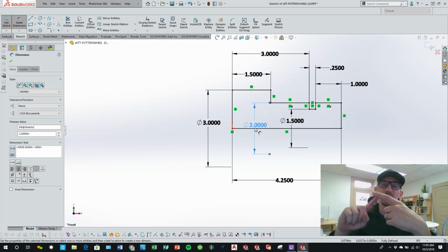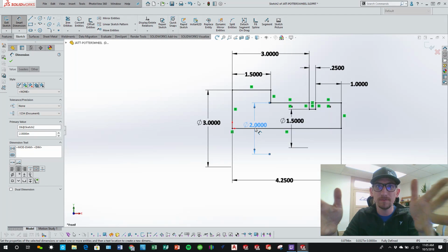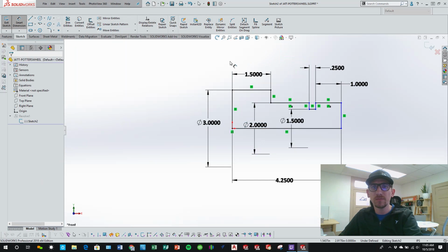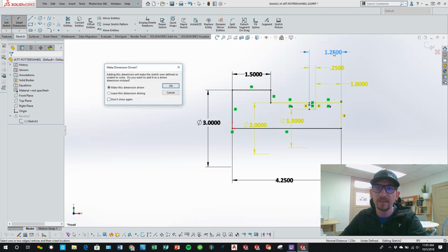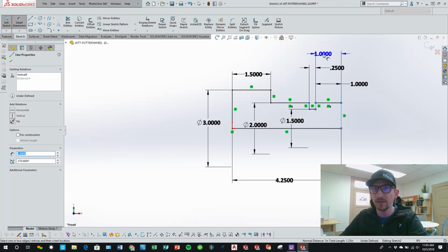Okay, so moving along here, this is a very good pro to the potter's wheel. Once again, we are using 2D sketches to drive the parameters of my part. I am not affecting my overall design intent, saying that, hey, this has to be 4 1/4 and I don't want my groove out here to change at all. Pretty awesome to set it up that way. Now instead of that 3-inch dimension, I could have also dimensioned off of this side and said it always has to be 1 1/4 off or something like that. That is another route you could definitely go.